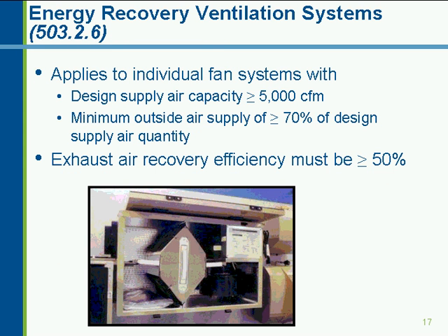There are requirements for energy recovery ventilators. This applies to any individual HVAC system that has a design supply air capacity of greater than 5,000 CFM and an outside air supply greater than 70% of that design supply airflow. The effectiveness of that energy recovery device must be equal to or greater than 50%.